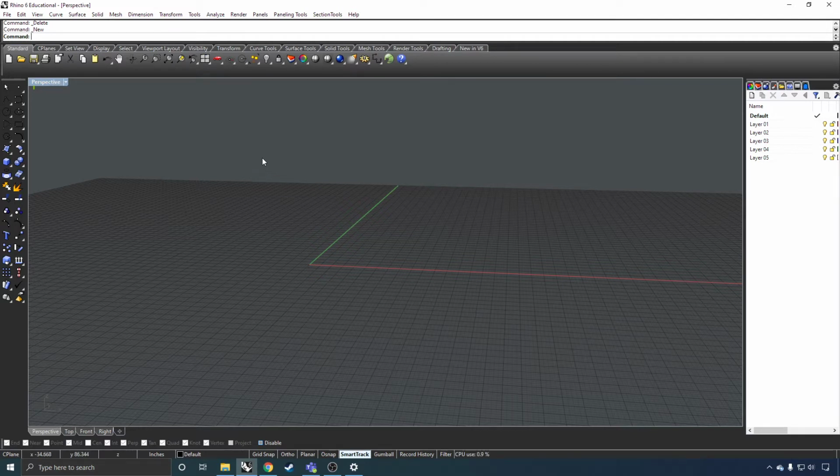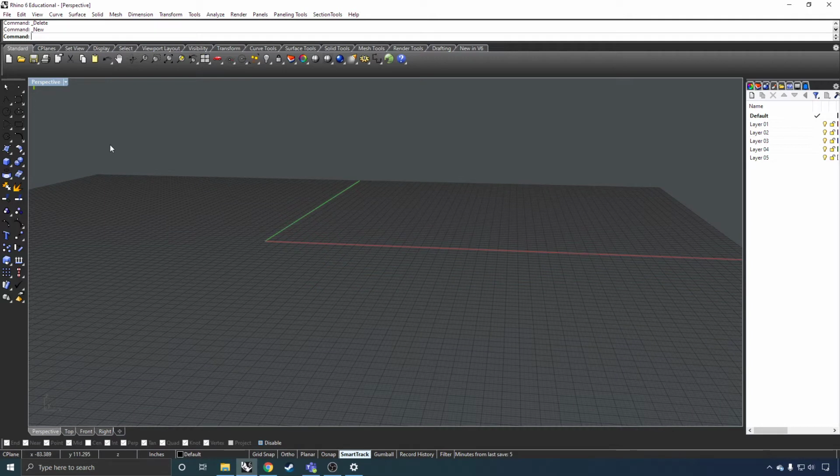The first thing I want to show you is how to make something simple. We're going to go with a line. I primarily work in the command line, so that's going to be this area up here. If you've used AutoCAD, you've probably gotten familiar with working with the command line interface. If I just type in the word line, it's going to give me a whole set of things that have the word line in it. I want just a normal line. And it will tell me what I'm supposed to do at each step of the way. So it's asking for the start of the line.